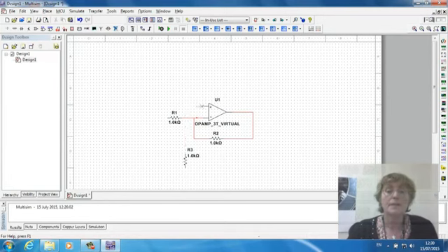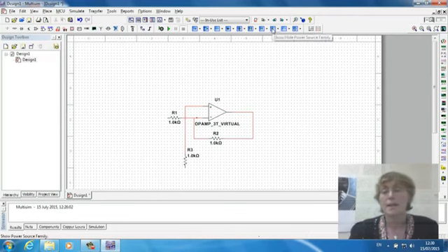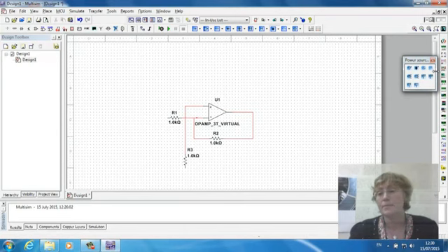I'll put that there. Multisim circuits always need a ground point to work. So even though your circuit doesn't have a ground, you have to put one on somewhere for Multisim. This circuit does have a ground. This resistor here should be grounded. So we'll get our ground from the power source family, and we'll use the analog ground here.